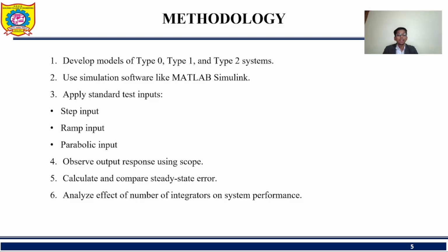These systems were designed and tested using MATLAB Simulink software. After designing the system, we apply standard inputs such as step input, ramp input, and parabolic input to check the performance. The output of each system was observed by using a scope to understand how it responds over time. Then the steady state error was found by comparing the input and output values after the system becomes stable. Finally, all the results were compared to see how increasing the number of integrators reduces error and improves system performance. This is all about methodology. I will show you the actual simulation.